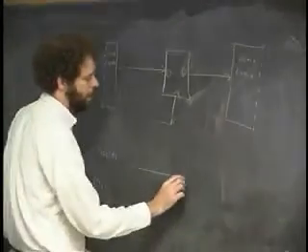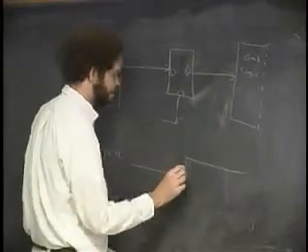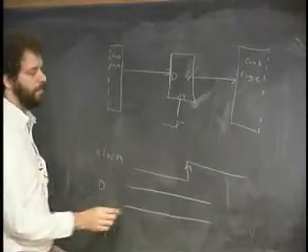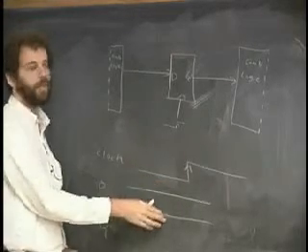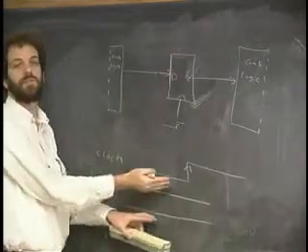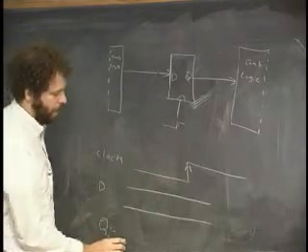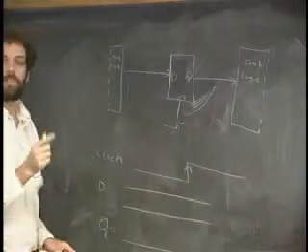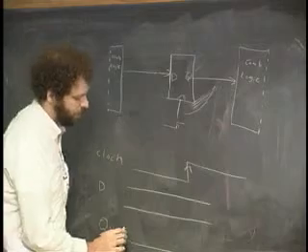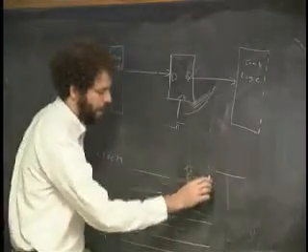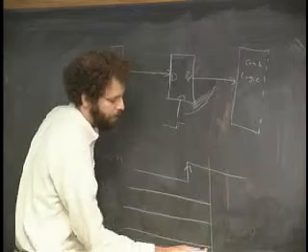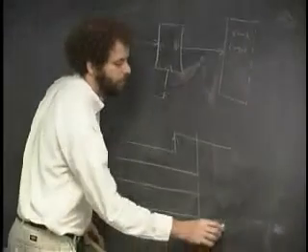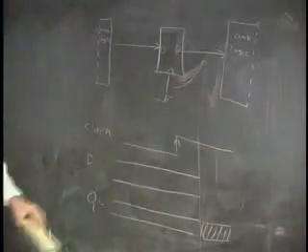So the clock goes from low to high, like so. Okay? And I'm assuming that the D value is going to be stable around that time when the clock goes from low to high. It will either be a high or a low, and there can be many bits here. So all I mean is that the bits are all set up. The Q, after the clock goes from low to high, a short time after that, what happens first? The first thing that happens is the Q, which also used to be either a high or a low, a short time afterwards, Q goes from that high or low value to an intermediate value, which we don't know. In other words, the old value of the current state is erased from the board.